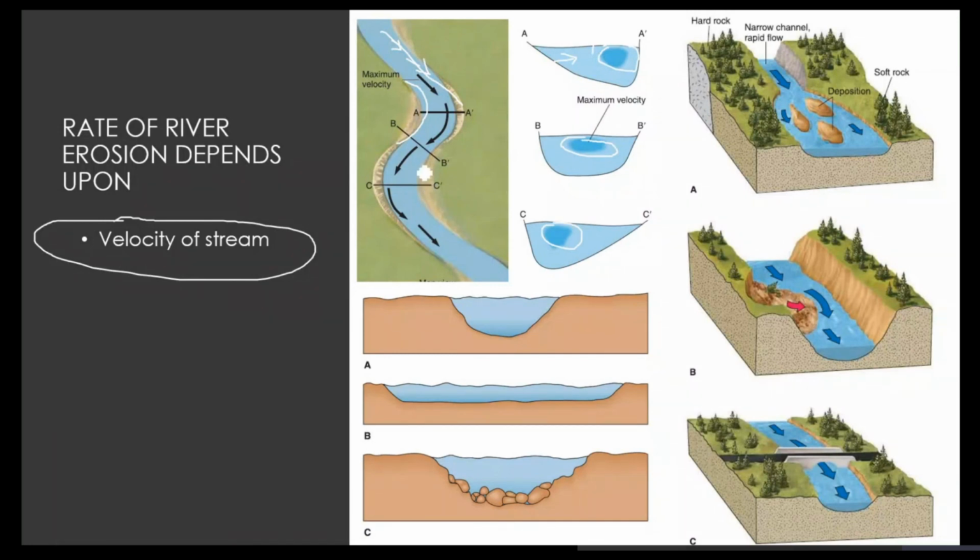If you remember the first lecture, the introductory lecture, I was talking about the Hjulström erosion process. That is this criteria. When there is more velocity, there would be more erosion. Where there is less velocity, there would be more deposition. Correct? So this is the process that happens. So velocity is one part which controls the erosion nature of the river.